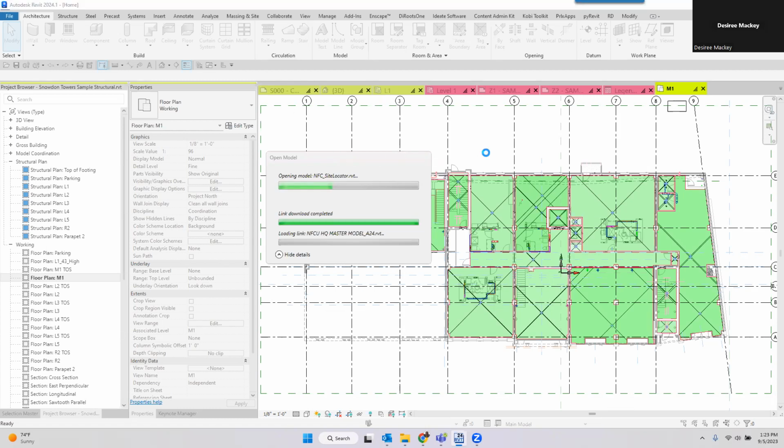So once I've done that, now I've acquired the coordinates and it's set up there. The reason why I do it this way is that somebody's going to come back in, 6 months, 3 months, whatever, and say, sorry, we've got to rotate that building half a degree, or we need to elevate that building by so much. We need to change where it is on the site. Again, I just go back to my site locator. I reposition that building, realign the grids in the site locator file to it, save it, go back to my building, reload that site locator file, realign, and then reacquire coordinates.